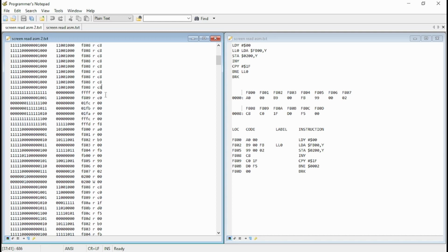So typically, I'm not sure it's always the same, but effectively we're seeing here this FFFF, and then it goes through here. The important point is it then goes to the reset vector FFFC and FFFD. And you remember we saw in the hex file that was 00 and F8, which gives us the address of F800 for starting our program. So that's where it then starts picking up the program that we're going to execute.